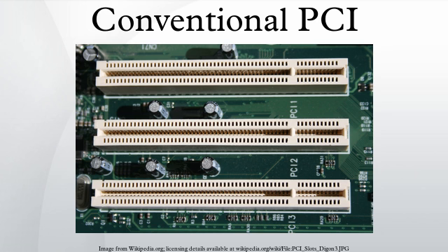If two initiators attempt the same transaction, a delayed transaction begun by one may have its result delivered to the other. This is harmless. A target abandons a delayed transaction when a retry succeeds in delivering the buffered result, the bus is reset, or when 2^15, equal to 32,768, clock cycles elapse without seeing a retry. The latter should never happen in normal operation, but it prevents a deadlock of the whole bus if one initiator is reset or malfunctions.